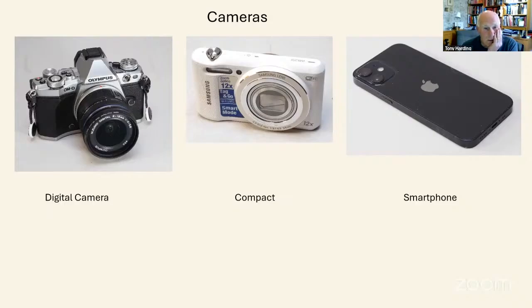So let's get underway with this sort of virtual building survey then. What I do generally if I'm going into a building is start off with some general views, and they don't need to be particularly well considered or technically high quality shots. They're just views around the four walls of the room, just as an aid memoire for people that are making sketches or starting to draw up plans of the general layout of the room. And also a bit of an aid memoire for me as a photographer.